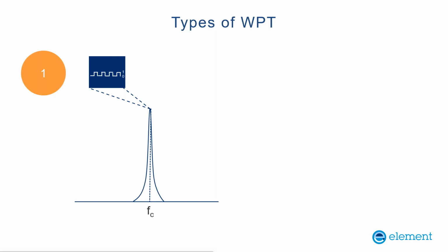So in the example that I've got on the screen here, the carrier frequency has got a form of modulation. There is just one carrier that is brought up, and within that carrier that is modulated, and the reason for modulating that is to provide a communication link with the load itself to get feedback information like what is the battery status, maybe some health and usage information about the load as well. But fundamentally, there is some intelligence in that signal.